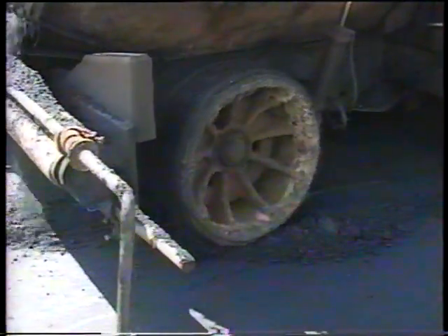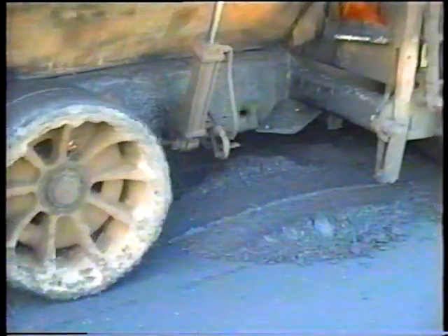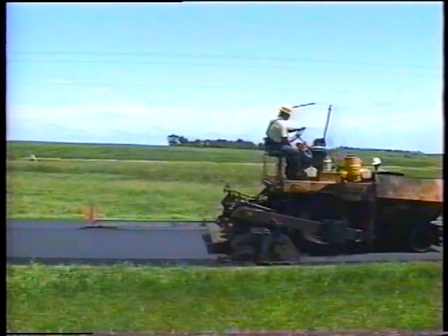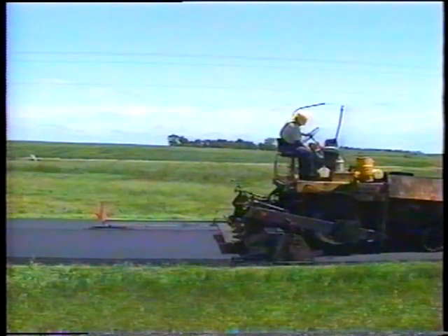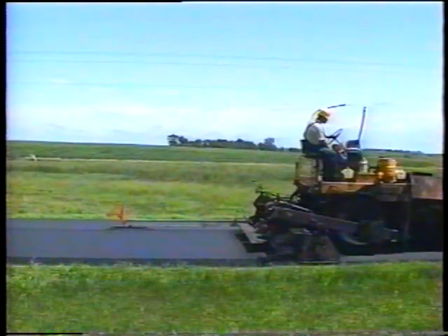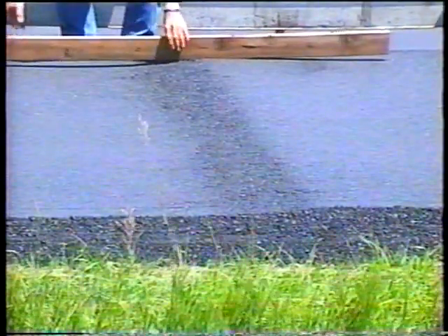Even though most screeds respond to the sensing device, they are still attached to the paver. If the paver suddenly rises, it brings the screed with it, before the screed can adjust, leaving a corresponding bump in the pavement. Here, for our dramatization, our pile of spilled mix created a virtual speed bump.